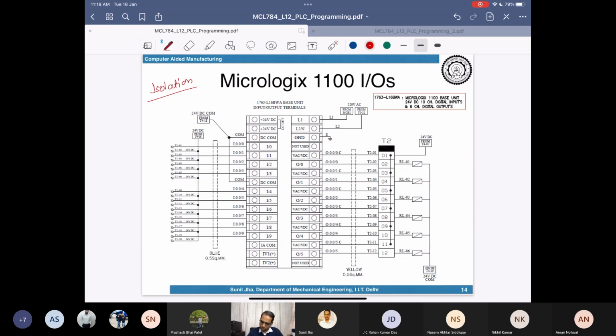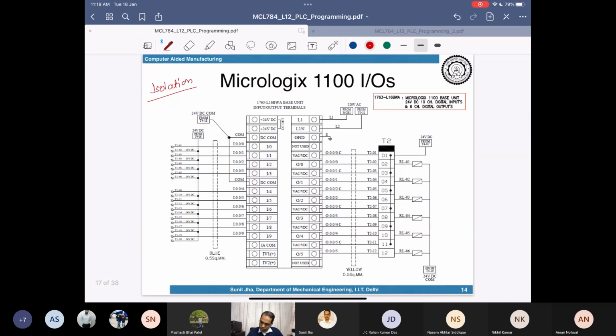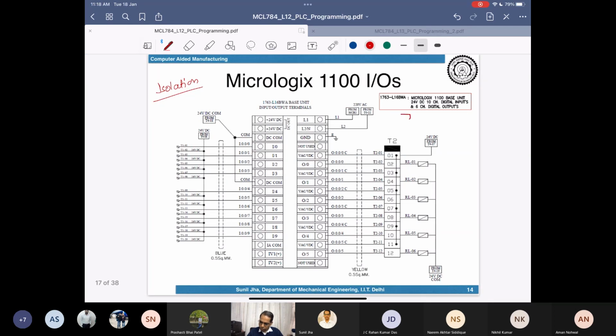So in an electromagnetic relay, let me quickly draw it and then show you here itself. So an electromagnetic relay is like this. You have coil terminals like this. There's a coil here inside, it's an electromagnet with a coil. These are the coil terminals, which we call A1, A2. And then there is an armature, which is floating here with additional terminals, which we call contacts. So you have 1 and 2, these are the contacts. And there is a mechanical spring, so this is the coil and this is a mechanical spring, which will keep this in contact or in touch with one of the terminals.